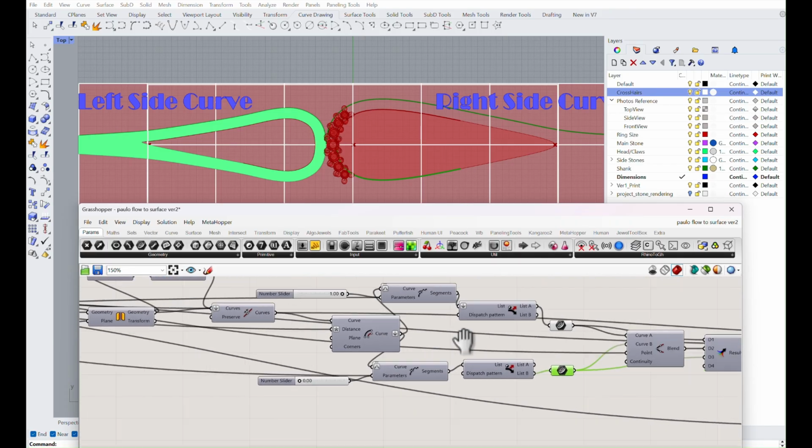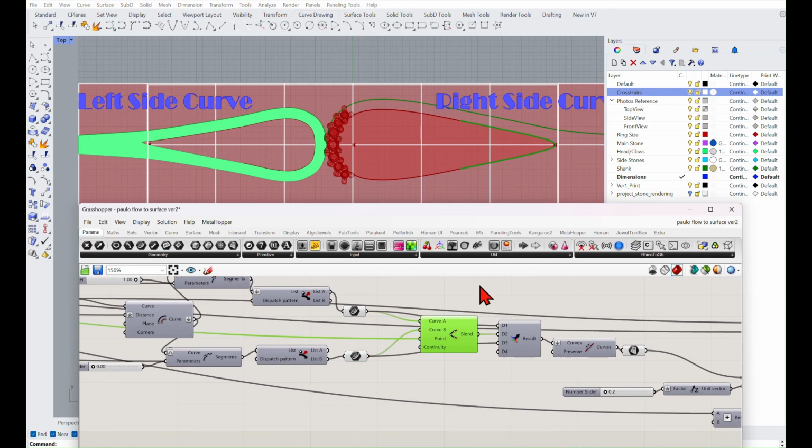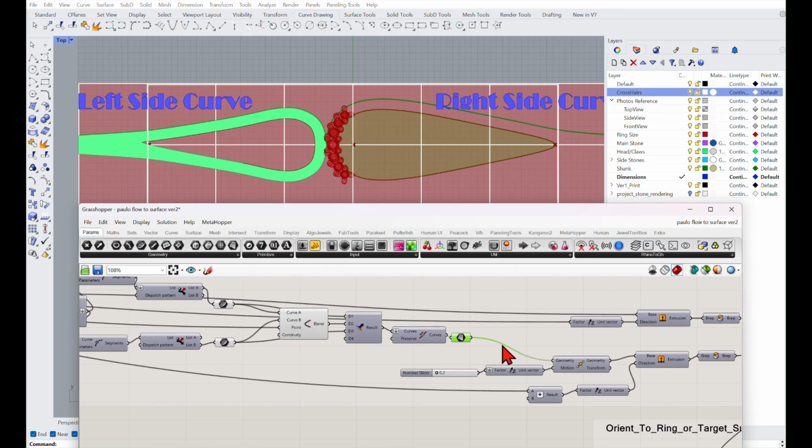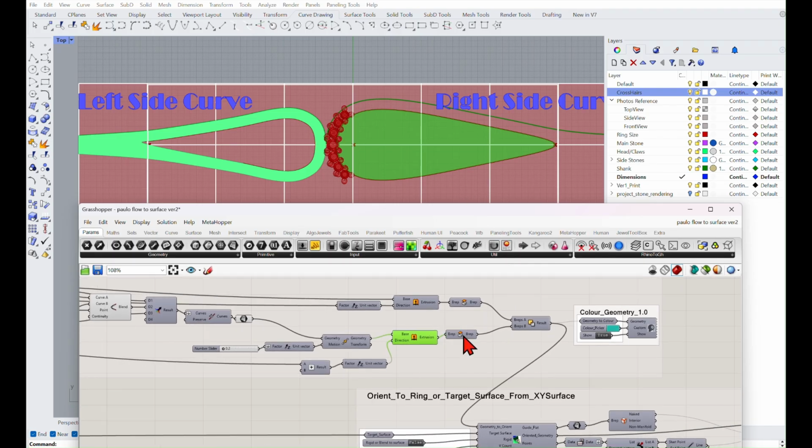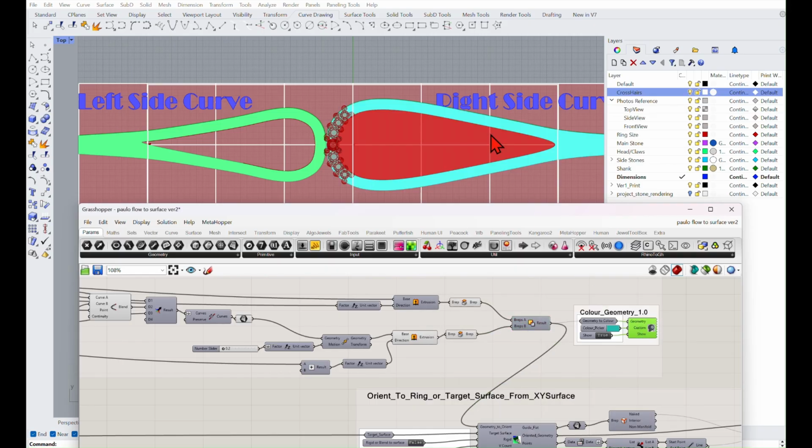And then we're bending between the curves here. We're lining them up and joining 1, 2, 3 curves to create the surface. And then we're extruding the surface, capping it, and taking a Boolean difference between this solid and this solid. Between this solid and this solid, giving us this solid. Okay?